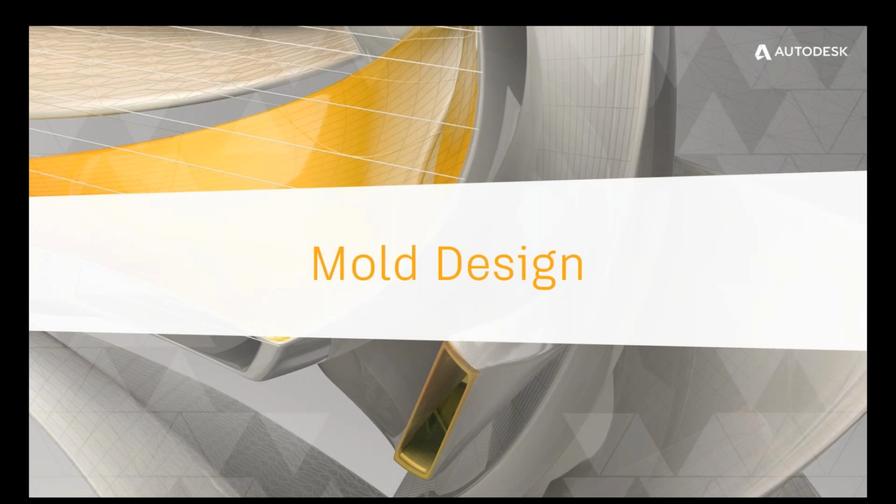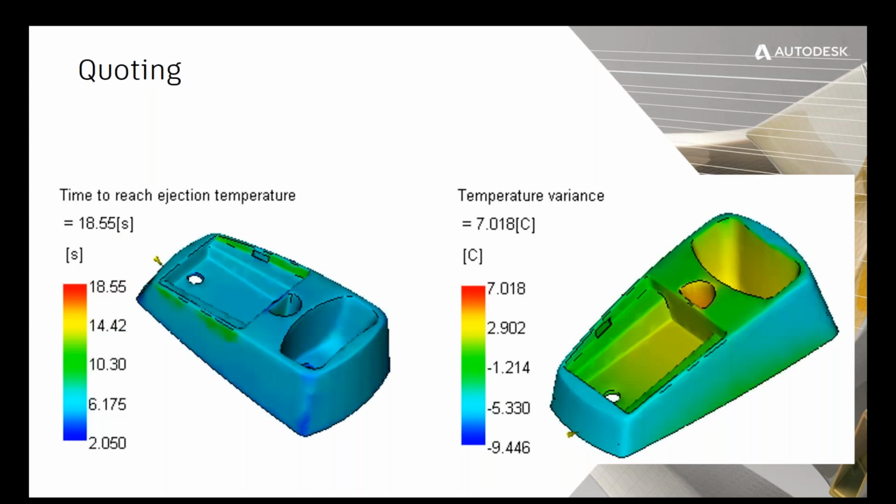From part design, let's now talk about the actual mold design phase. Initially, a job may need to be quoted, then the real fun begins. Oftentimes we hear of customers using experience, which is great, but missing the mark a bit. I was just at a customer not too long ago and they mentioned no quoting jobs for various reasons. Using Moldflow, you can predict the time to reach ejection temperature and temperature variation across the part, thus better predict the cycle times.